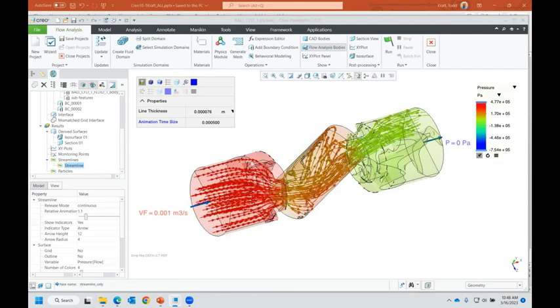There's a few people I could put you in contact with to get the streamlines onto your model. The trick is to export the streamlines as IGES files, and then we have a custom shader that can shade them accordingly with the correct velocities, and put them next to your model, and then you can make an experience with the streamlines on your model. So that's available today. It's not customer viewable. It's something PTC can do, like Steve Wall and a few more AR experts.